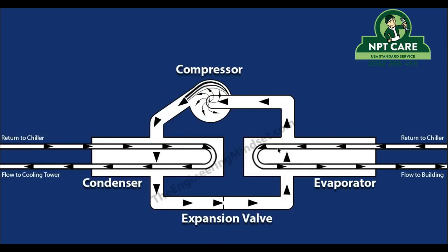You might be wondering about what's happening inside here. So the evaporator, or the chilled water circuit, is the water, if you remember, it's being sent up to the AHUs to collect the unwanted heat from the building, and that's returning at about 12 degrees, and it's coming back into the chiller, passes through the loop, and by the time it leaves again, it needs to be around 6 degrees. Obviously the temperatures can vary a bit, it depends on the setup and design of your chiller, but this is for explanation purposes.